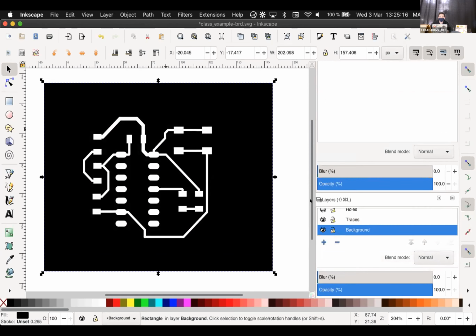Let's finish all with the holes and the outline first, and then we export all of them together. This is important. When we are exporting, we need to export them at the same size, because if they don't have the same size, when you calculate the different strategies, they will be moved. So it will not be aligned when you cut the different things. So always export with the same size. For this reason, I want to have the outline also.